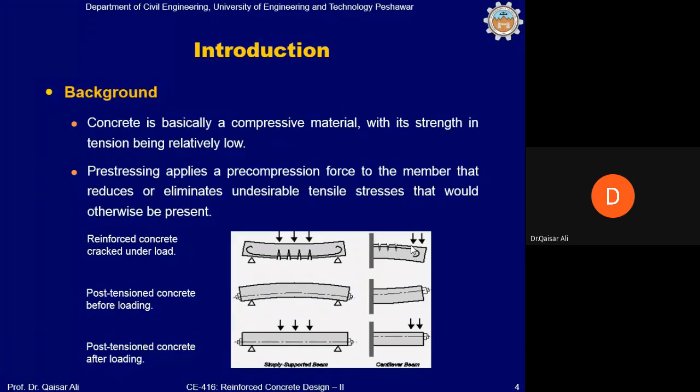So when reinforcing steel and concrete are perfectly bonded, any strains which were produced before introducing reinforcing bars in concrete would now be taken by the combined action of reinforcing steel and concrete, thereby avoiding cracking and collapse of the concrete beam. So the problem in all these situations was the tensile stresses produced.